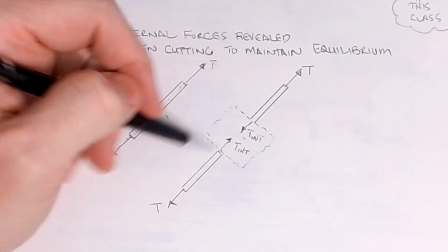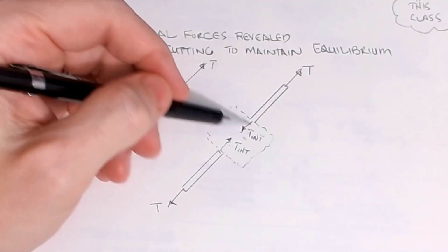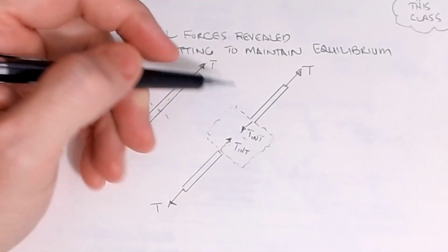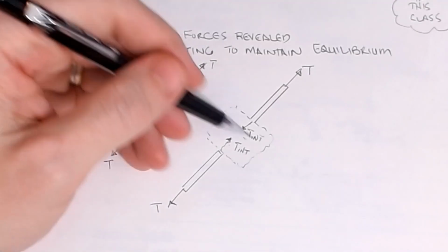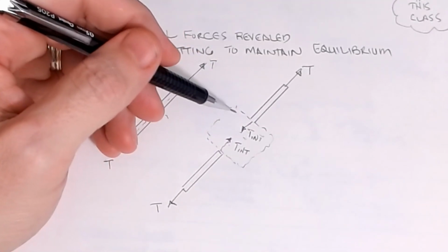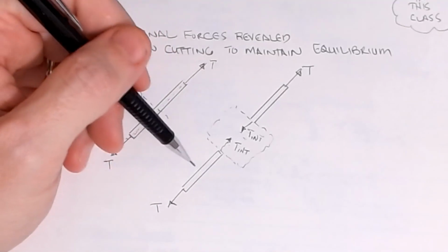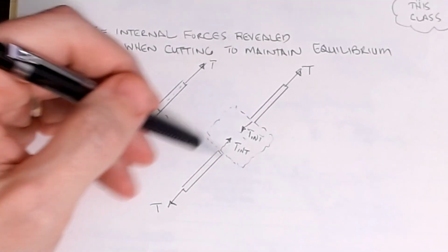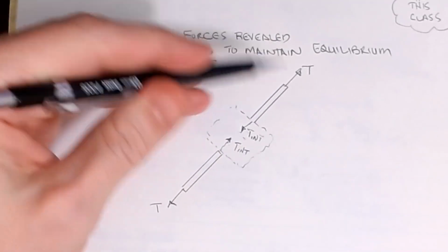All right, so this is what we call an axial member. In more complex problems, you can get additional forces and even moments that show up as internal effects as we start to look at it. And we'll talk about those more as we get into some of the applied problems later in the series. But for now, this is the idea of what an internal force is. You've got to have equilibrium at all parts, even after you cut them.